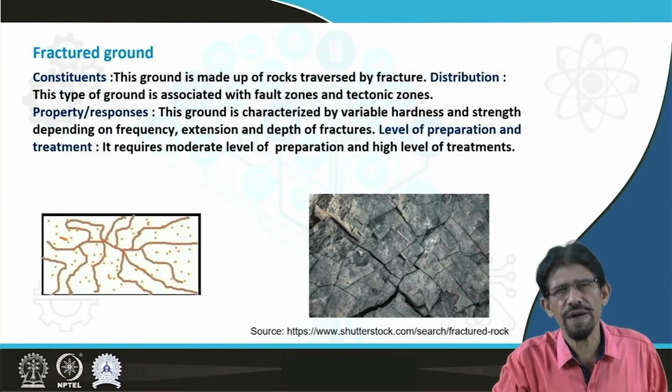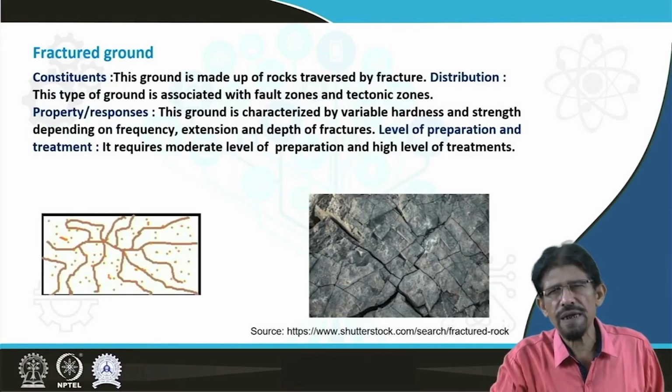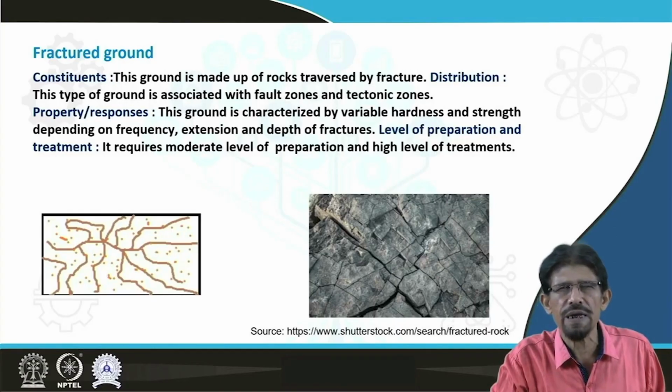Fractured ground, friends, as you know, as the name indicates, is any rock strata or material traversed by fractures of undefined pattern. If it is defined, then it is jointed. So fractured rock is weak in nature and shows variable hardness and strength depending on the frequency, extension and depth of the fractures. Therefore, the preparation requires a moderate level, but it requires a high level of treatment.